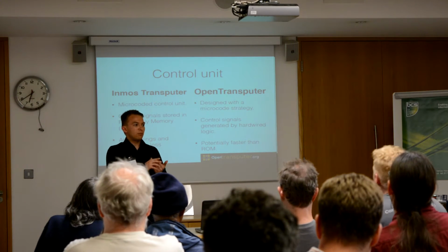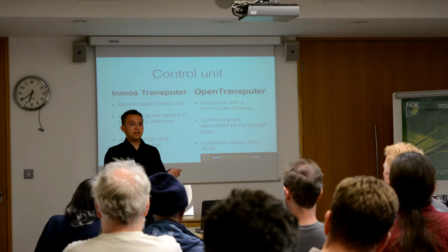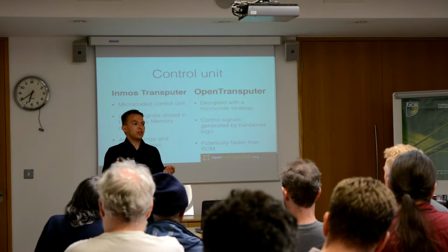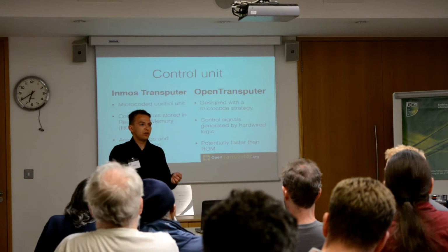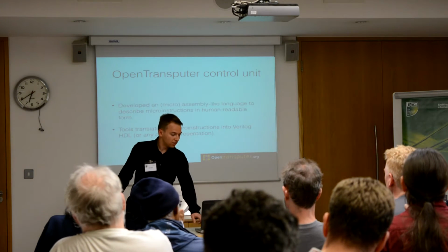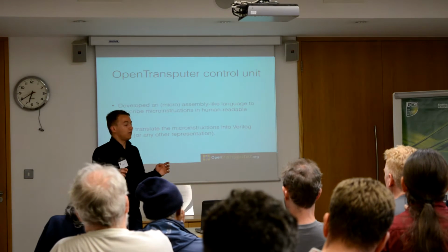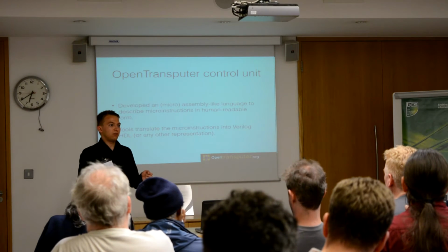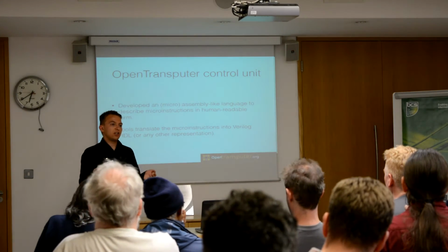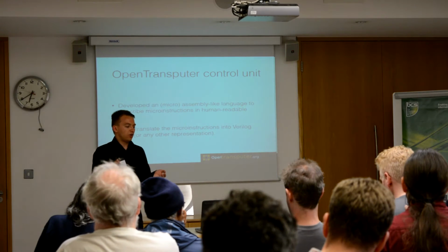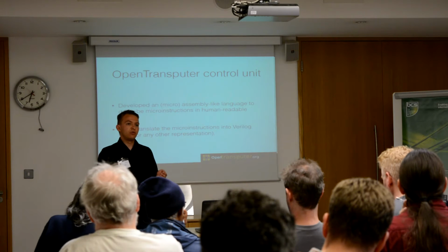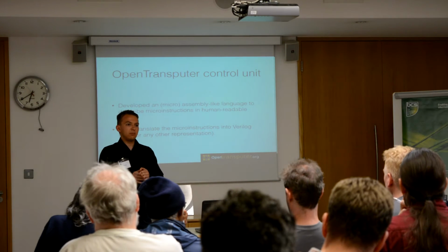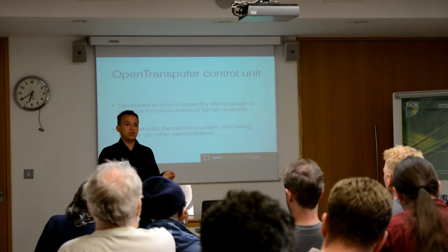We can modify them relatively easily, but we also get potential performance benefits because we don't have to keep reading from memory to get the control signals. To do this, we developed our own MicroAssembly language, which is essentially a human-readable format of the microcodes and micro-instructions. And then we wrote our own tools to take these MicroAssembly instructions and translate them into actual Verilog HDL.